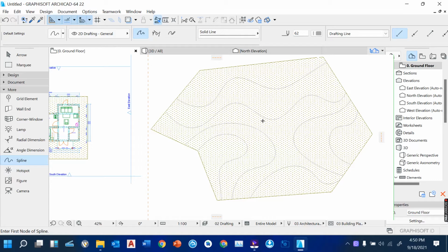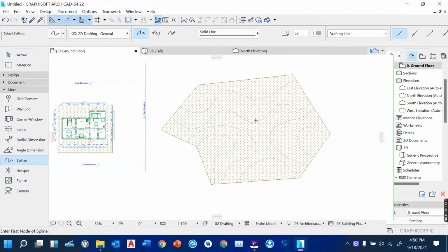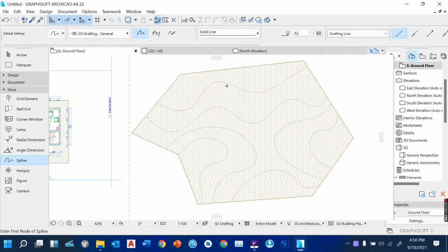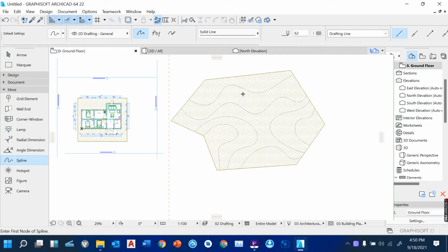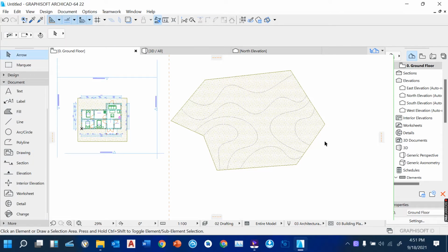So once you've used your spline tool, now we want to create points for using the spline tool so that we can have elevation, so you can see how our mesh is not flat. So we can have a rugged piece of land. So after you have drawn your spline on the mesh, you come back, use the arrow, and select everything.